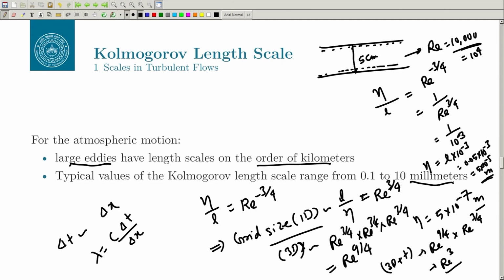And if it is proceeding, that means that it is getting dissipation from somewhere, okay, either the numerics may have a lot of dissipation, and that is why the solution is continuing. But in that case, you may not know where it is cutting off. I mean, if you look at this E k versus k, it might be cutting off here, which is maybe right in the inertial range, right, and then it may give you a completely wrong result, it may basically kill the scales which are very, very important, right.